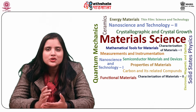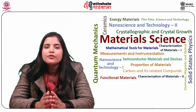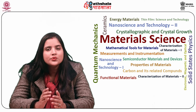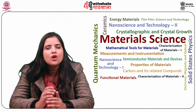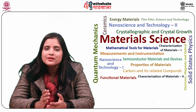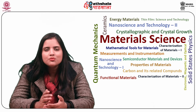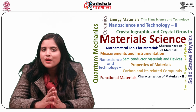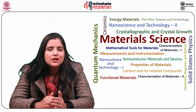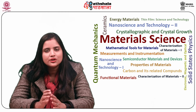Gas is continuously purged through the chamber such that the gas flow moves the evaporated metal away from the hot element. As the gas cools the metal vapor, nanometer-sized particles form. These particles are liquid since they are still too hot to be solid.